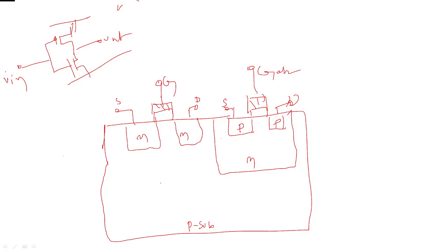And here we are giving the extra biasing, that is body biasing, and using that we can control and reduce the threshold voltage for this. We can reduce or increase it: using forward bias you can reduce the threshold, and using reverse bias you can increase the threshold voltages for the two transistors, one NMOS and one PMOS transistor.